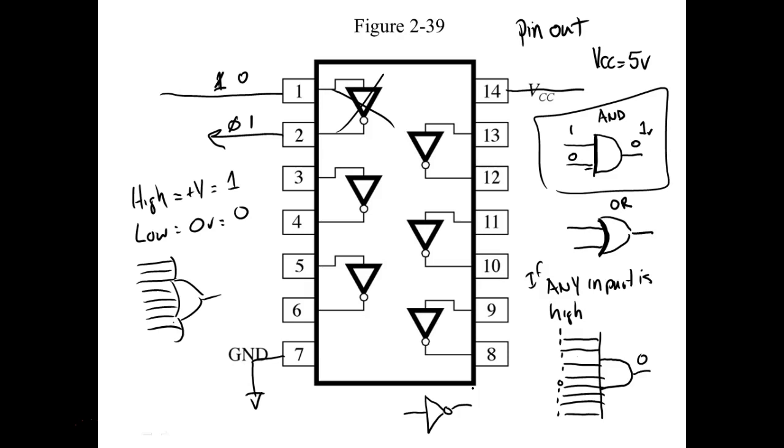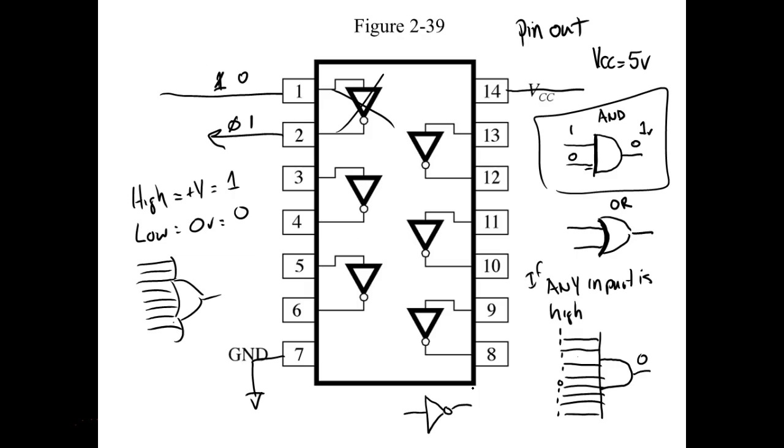So those circuits are nice. Like I said, I could draw the input of an OR gate. I'm going to show y'all on the next slide the actual TTL circuit. Because you have to understand, we don't troubleshoot this from a component view. Well, the IC itself is a component. We troubleshoot it based on what I expect on the output, depending on the input. If my output does not respond to my input, I might have to troubleshoot a little more, right?